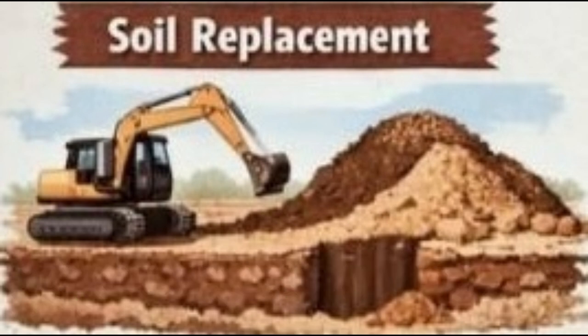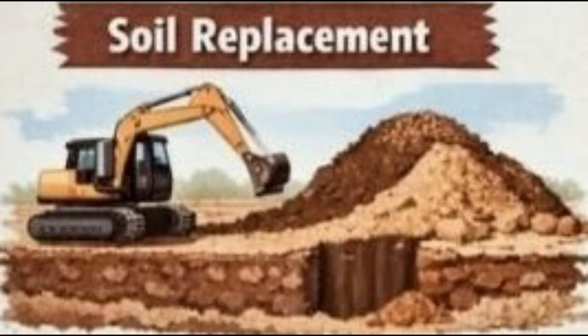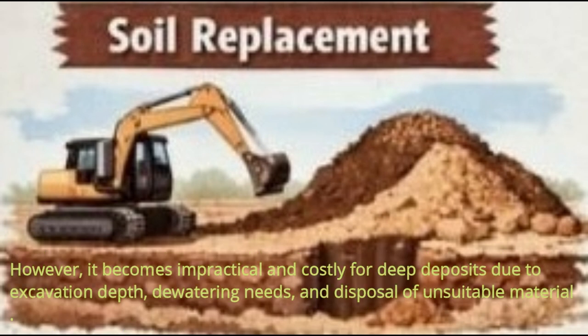By physically removing the problematic soil, the foundation rests on a more competent layer, leading to immediate improvement in bearing capacity and reduced settlement. This method is most effective where weak soils are shallow. However, it becomes impractical and costly for deep deposits due to excavation depth, dewatering needs, and disposal of unsuitable material.